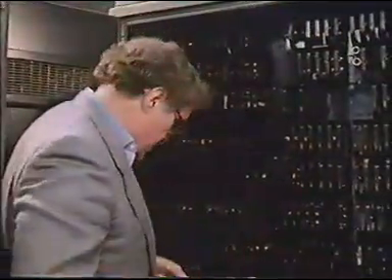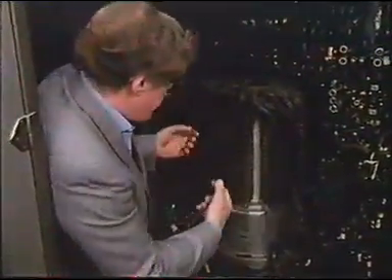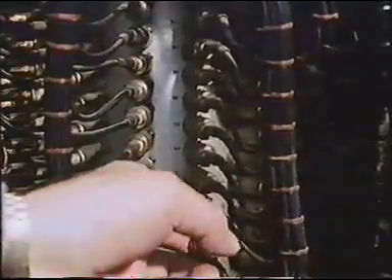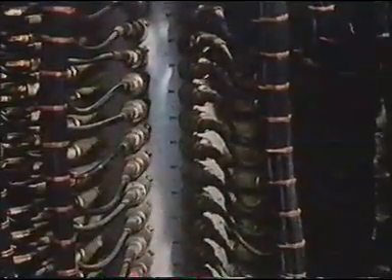It's a digital computer. That means it operates in binary. The numbers are carried in binary notation. In other words, a series of ons and offs. The backing store of this machine is this. It's a magnetic drum. It's rotating around here at 6,000 revs a minute, and on that drum is recorded the binary notation, binary numbers, and it's read off by these read heads here, one on each track.